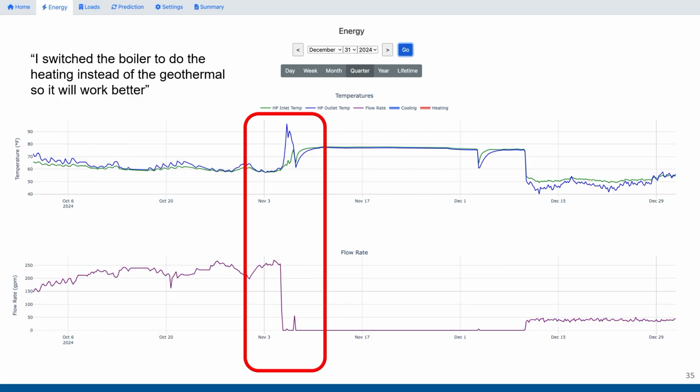The first thing we noticed was that it was in January, and the loop temperature was 60 degrees. Then we found there was a boiler on the system, and the sequence was completely screwed up, and it was trying to maintain a 60 degree loop temperature. We worked with the controls contractor to write a sequence that would let the backup just do backup.